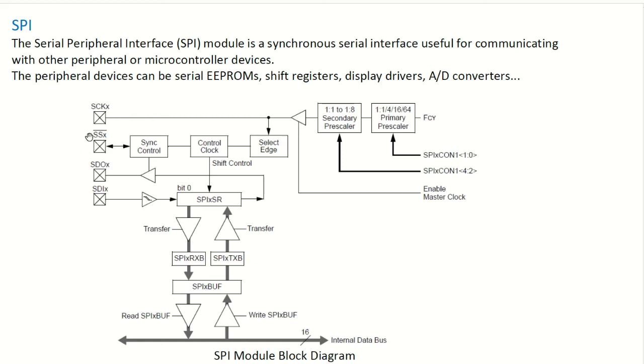What you need is how to decode this information and how to code it, because from this signal you can extract the variables. For example, for the MAX6675 thermocouple, you have libraries that give you the information directly in terms of numbers representing the temperature. So you don't have to bother yourself with how to do the conversion.